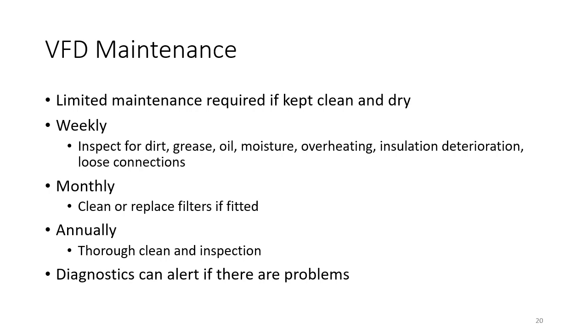So if anything goes wrong with the VFD, then you can use the front panel display, or you could use the communications, or you could plug in programming and configuration software, and that can be used to find out what happened to the VFD. Is there a failure in the internal electronics? Was there an overvoltage? Was there some other problem?